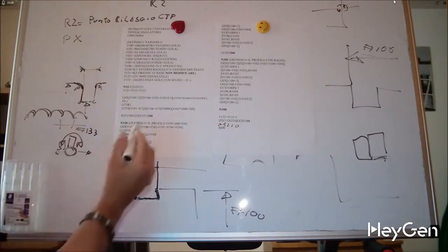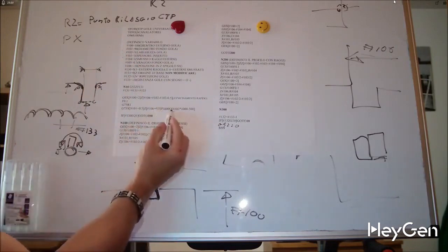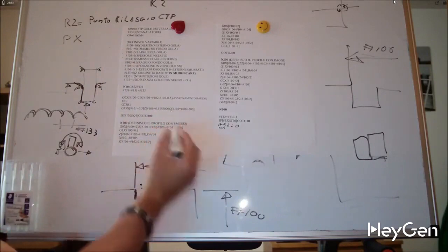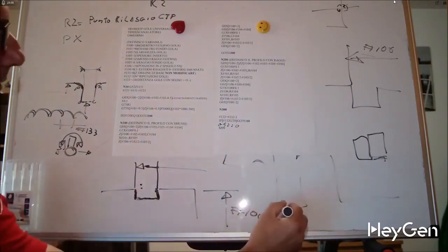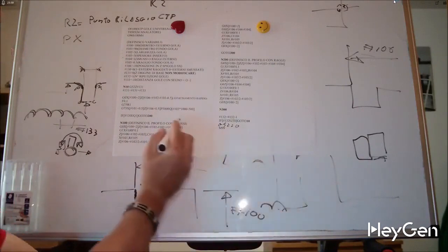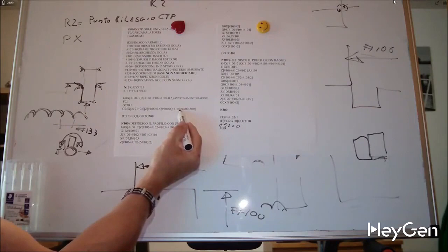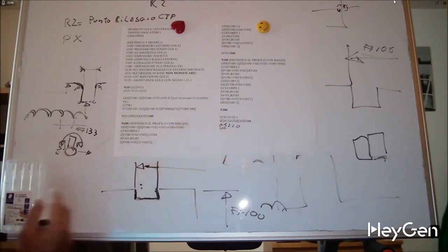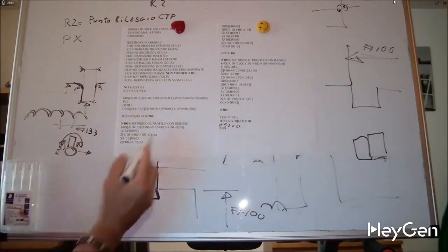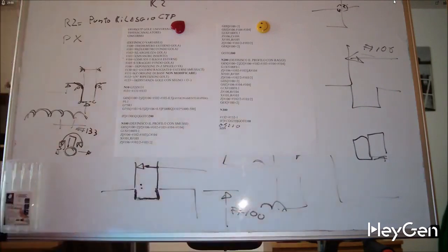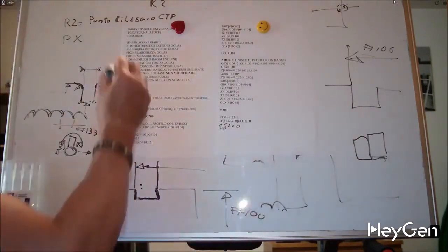set how much the insert will move each time it widens the groove. And how much the insert will move, of course, is in thousandths of a millimeter of its thickness. So its thickness of 3 gets converted into thousandths. So 1000 minus 500, which is minus 0.5. Therefore, a 3 mm insert will move by 2.5. A 4 mm insert will move by 3.5. And a 5 mm insert will move by 4.5.